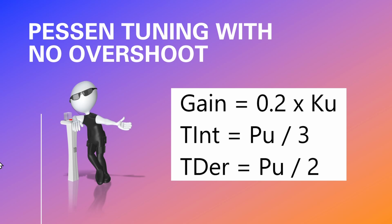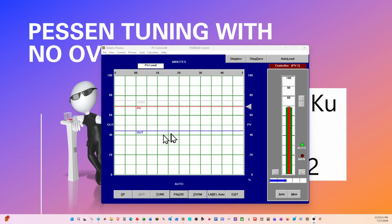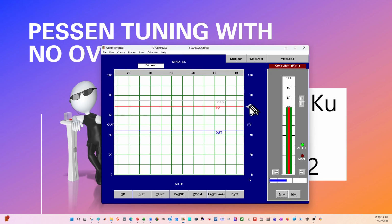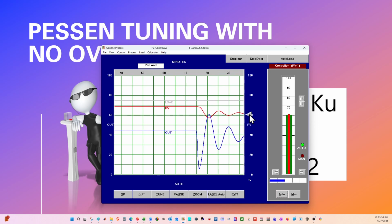I must say that this method doesn't always give me the exact results. So in many cases, you might just want to fine tune it afterwards. But nonetheless, we're going to implement it and see how we can get it to work. We have said that this is a closed loop tuning method, which means that the controller must be in automatic. We start off with a low gain value and give it a step change and look at the response, with the aim of getting continuous cycles and continuous oscillations.